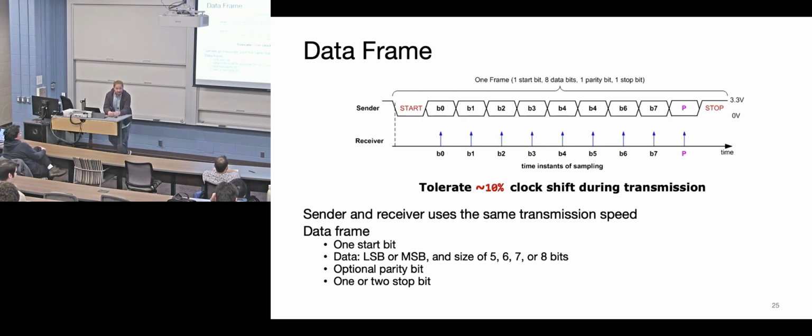Yeah. Can both sides start a transmission at the same time? Sure, they don't care. It can be completely asynchronous. Remember, inside these things is really just shift registers. So serial comes in. When the internal thing has figured out that there's 8 bits in there, then it'll send a flag, and then it's going to take those 8 bits and put it in a buffer. And you can do something with it. But yeah, those two transmissions can happen at exactly the same time.